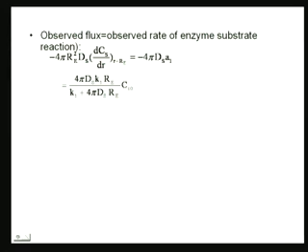Is that clear to everybody, Lisa? So, that is what we are trying to achieve. All these calculations are to find my actual reaction rate. You can have an intrinsic reaction rate, which is the ideal reaction rate that you would like to have, but life is not ideal, and the reaction rate that you get is lesser than that, and that is called the observed reaction rate. What we are trying to calculate here is how much less the observed reaction rate is than the intrinsic reaction rate.